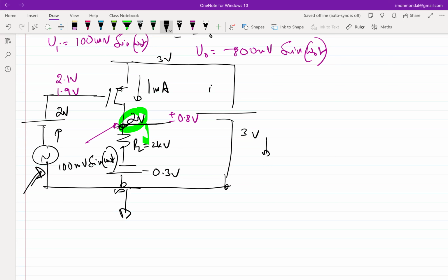So you remember the first lecture, second lecture, when we said that we want some output voltage to be constant regardless of load variation and all. And we ended up burning so much current in that load resistance that it became the problem. So if you are making a step down with a voltage divider, with a resistance, and that is supposed to take in any current, that resistance should be very low. So basically loading effect, right?